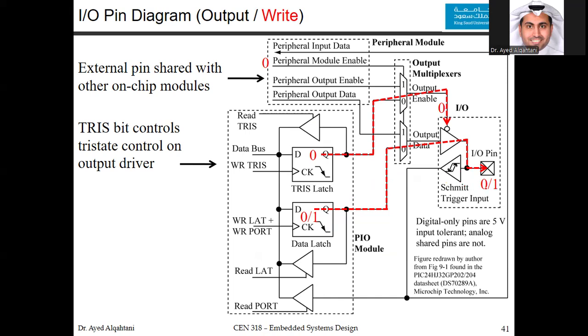You are outputting 1. Notice that we don't use the Schmitt trigger input here. It doesn't matter to us because this is the value that I just generated, and I'm sure that all the rising values and the falling values are as sharp as possible. Only use this if you have an outside value that comes from the outside, then you use it to make sure it is sharp.